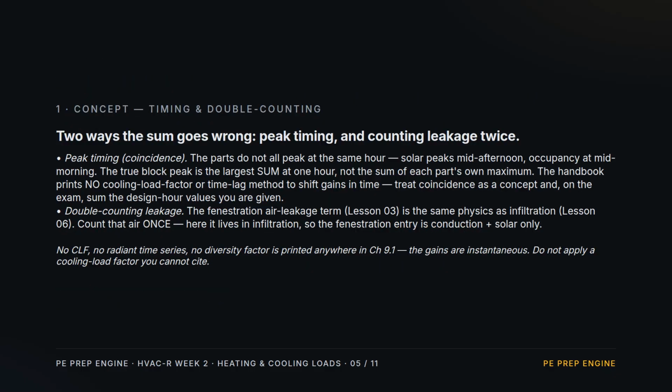Concept 4. The two ways the sum goes wrong. First, timing. The pieces don't all peak at the same hour. Solar peaks mid-afternoon, the crowd mid-morning. So the real block peak is the largest sum at one hour, not the sum of each part's own maximum. The handbook prints no cooling load factor or time lag method to shift gains in time, so treat coincidence as a concept and just sum the design hour numbers you're given.